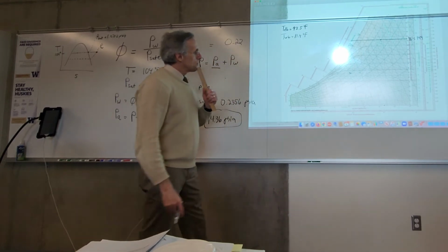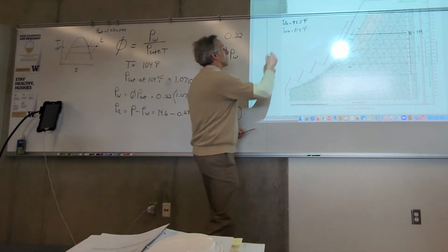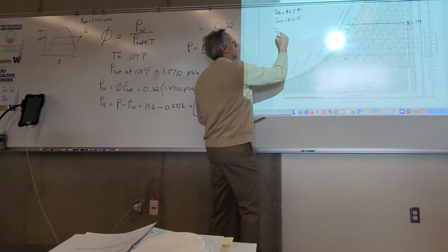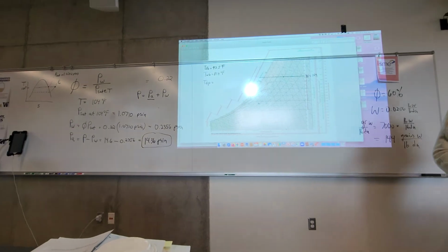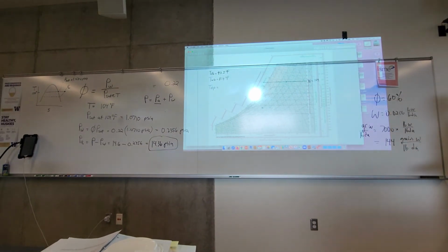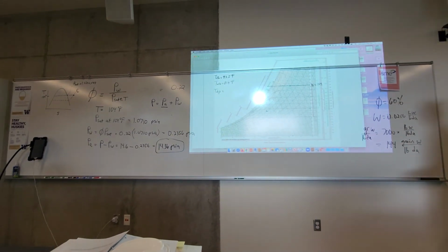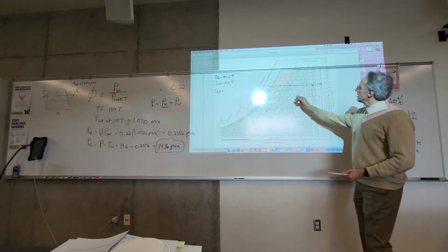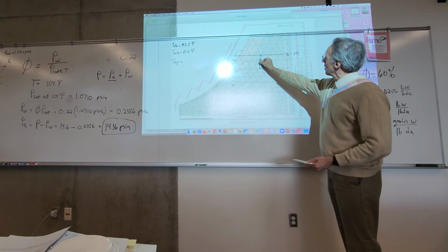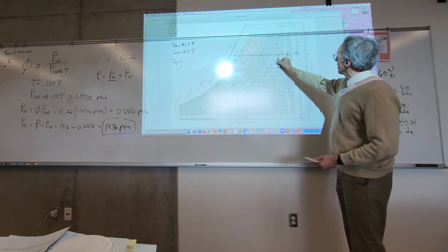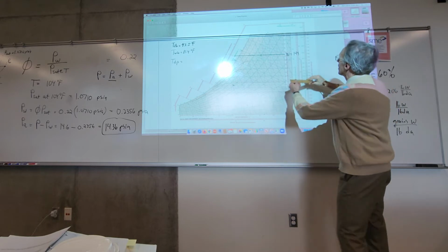Let's see, what else can we do? Dew point temperature. What do you get for dew point temperature? How do we get that? Well, this one's easy because you can just go to the right, on the same column where we found the grains. All the way over, because it has the grains, but it also shows the dew point right there.